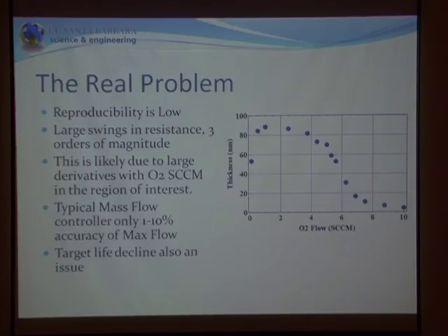And so in order to solve this problem, you essentially need to change your process parameters completely and make this region, in terms of O2 flow, as flat as possible. And there are 2 ways you can do that. So from the Berg model, you know that from the pump rates, you can bend this curve, but you also know that if you just increase your deposition rate, you can stretch it, and so hopefully that way flatten it so you can extend this curve in this direction.